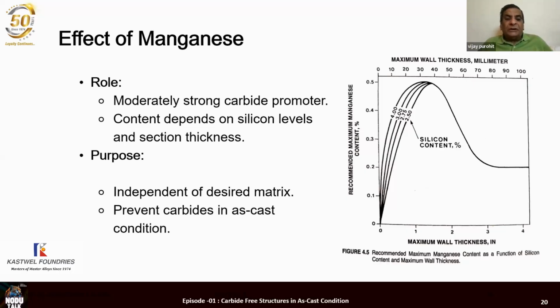You know why? Because whatever manganese is present in your liquid iron, let us say it is X% present. When that liquid iron solidifies into castings of heavy section, there is segregation of manganese, which segregates to 10 times this value. That means in the heavy section casting, the manganese will be as much as 10x. So if your liquid metal has 0.5 manganese, the heavy section casting will have up to 5% manganese.